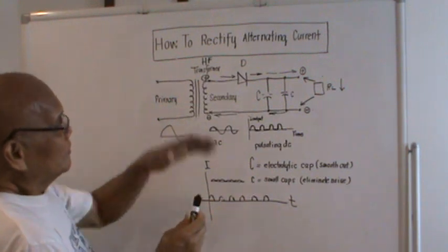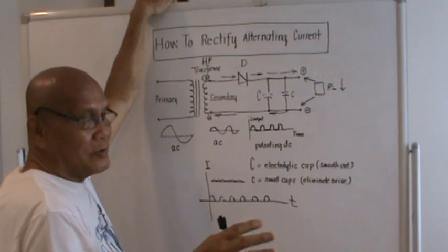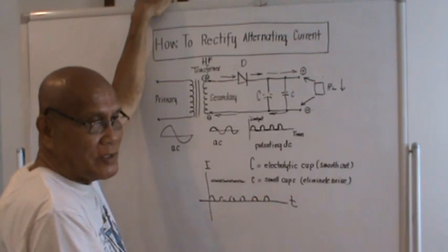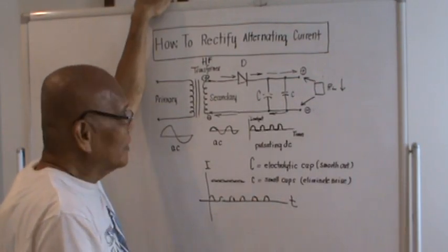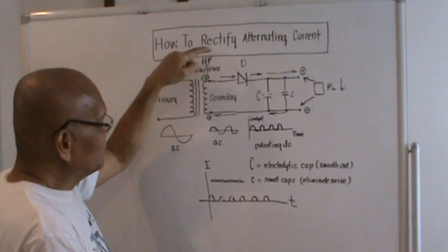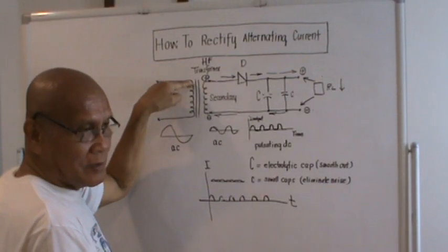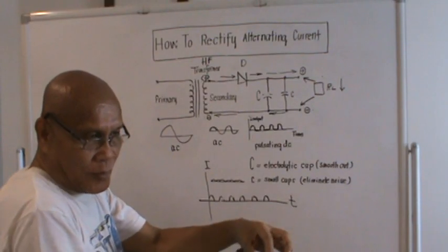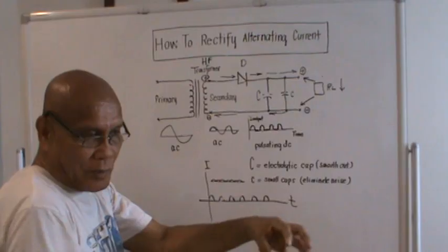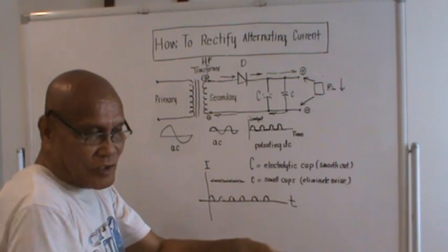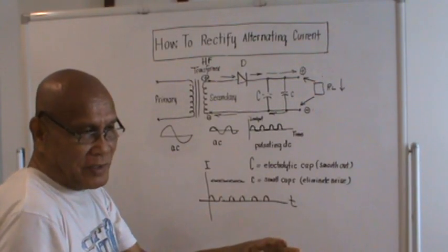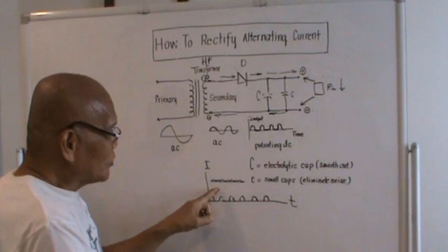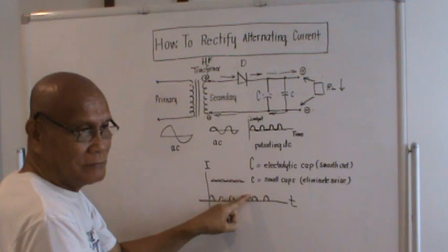So, to bring out a good DC voltage for switch mode power supply, instead of just using a 60 Hz frequency transformer, we use the so-called HF high frequency transformer. So if you try to inspect a switch mode power supply, there are so many high frequency transformers on the secondary side, and each transformer got a different frequency, so that if you try to rectify those voltages, of course the pulsations will be very small.